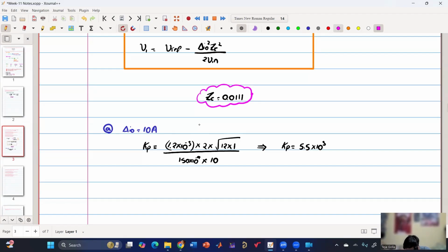As I was saying, sometimes we may get very high gains that may not be practically implementable. So we need to check in simulation and do thorough testing, to see whether with this high gain we can actually implement the optimal control. Also we have to see the maximum peak current it will reach during the transient.